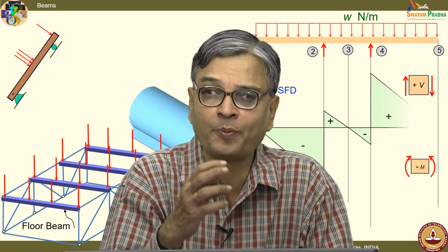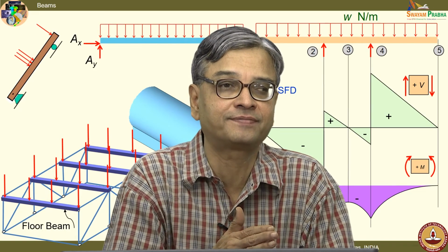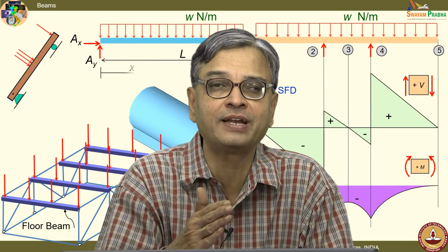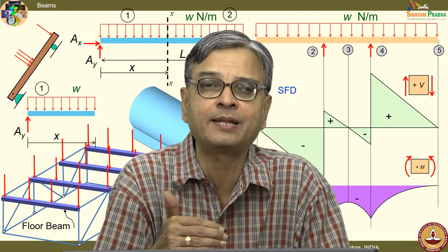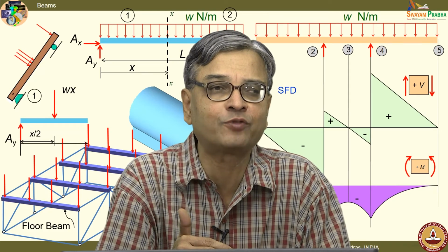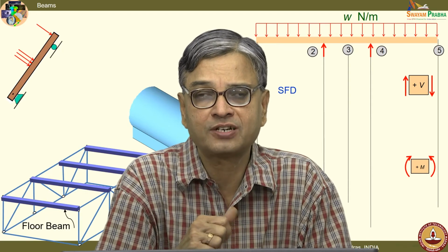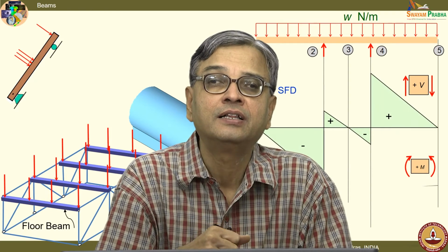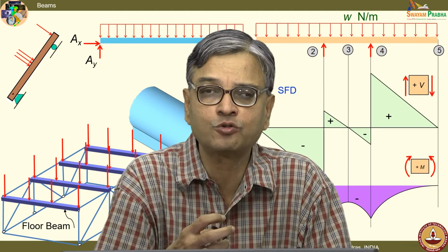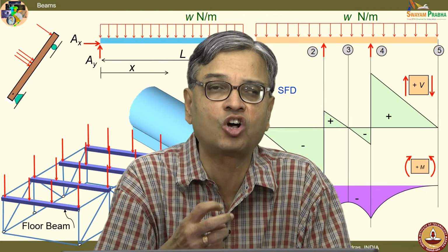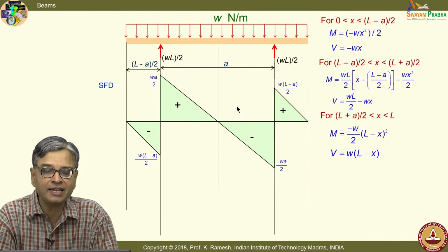So, when I have to find the optimal support, I must look at the variation in bending moment to take a decision. Shear force is only an intermediate step, and since you are learning how to draw the shear force diagram and bending moment diagram, we are drawing both for this problem. You have to keep in mind, from the stress analysis point of view, the effect of bending moment is very significant on the beam. The stresses introduced are much higher than the stresses caused by the shear force. So, do not get carried away by an illustrative sketch.